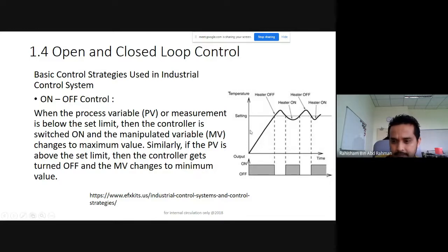What will happen when we turn on the boiler? The temperature starts to rise. Whenever it comes to the set point, it detects that it has reached the set point, and then it will immediately turn off. Gradually there will be a rise, and then at some point the temperature will start to decrease. When it decreases below the minimum, the boiler will turn on again. At the end of the day, this will regulate at this set point.